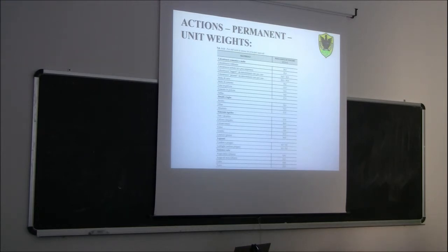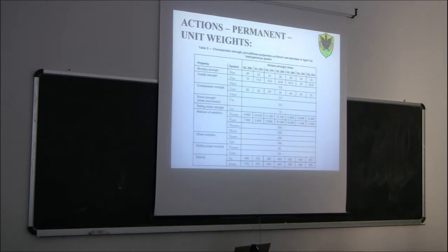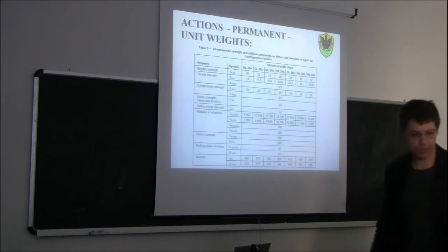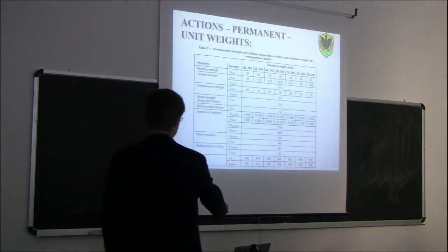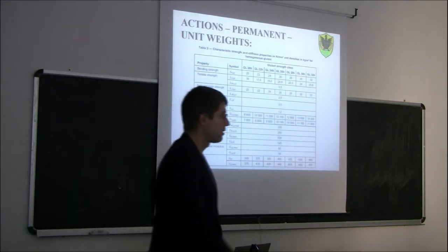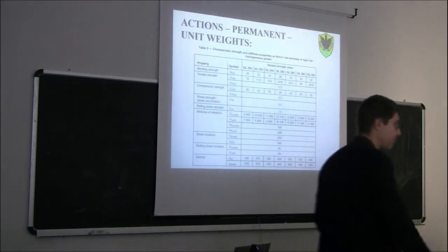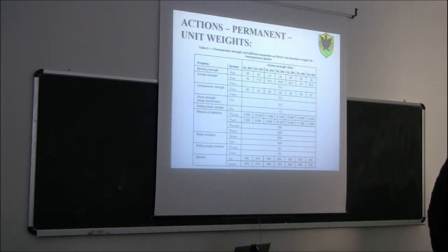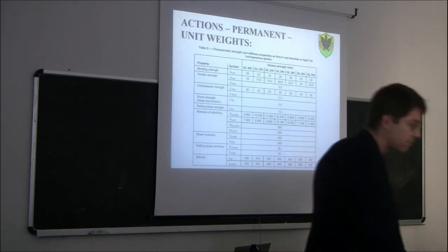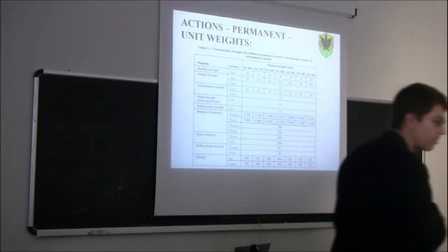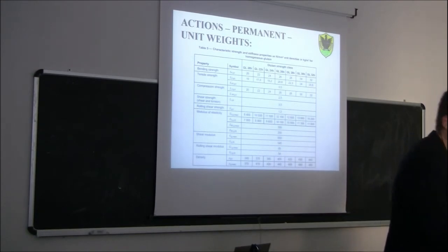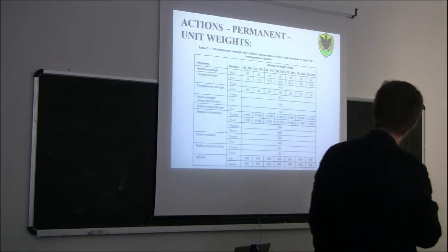If you want to be a bit more precise, you can go into the table about glue laminated properties. From this table you have two values of densities: the characteristic value and the mean value. So you have to select one strength class. For example, in this case we selected the GL28H. Do you remember what GL28H means? So GL means what? Glue laminated. 28.